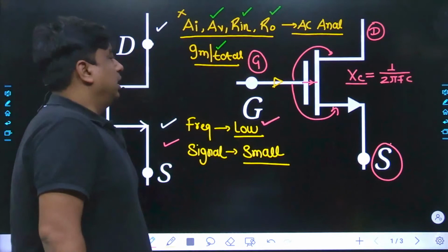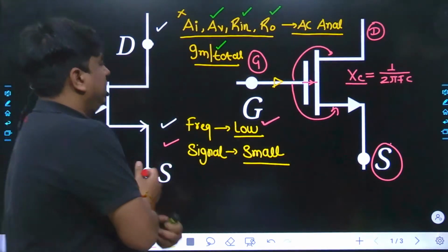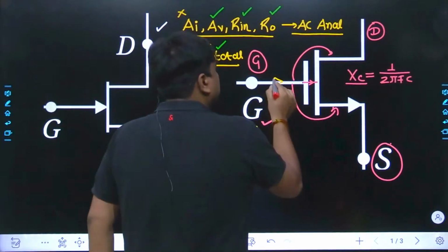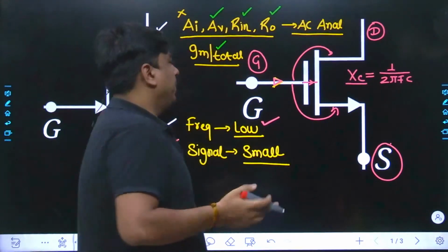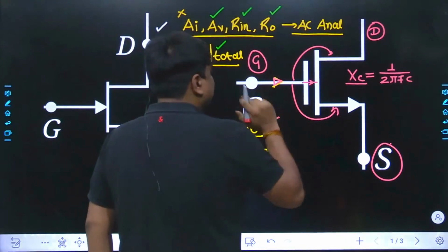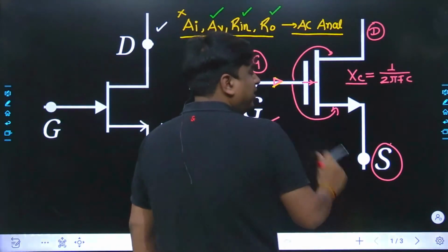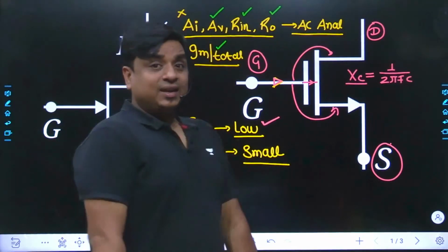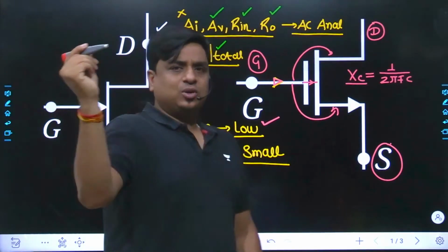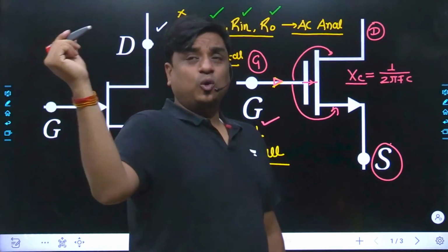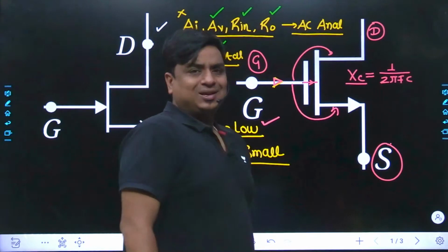Yes. Agreed till this point, I don't find any of the students would have any kind of doubts. My dear friend, I would like to ask each one of you, would it sink any amount of current? No. Physically we had already seen there is no conduction path from gate to source, because in between the silicon dioxide layer has been filled up, and the silicon dioxide layer has a very high insulating property. Virtually speaking, there could not be any conduction current which can go all the way from gate to channel. Obviously there is a blockage for the conduction current.